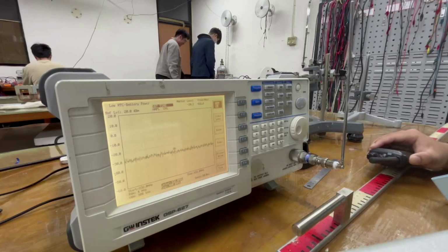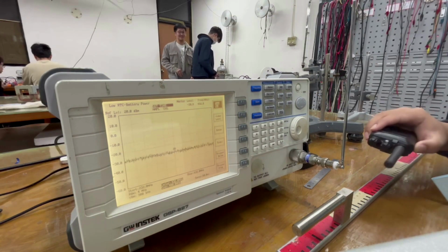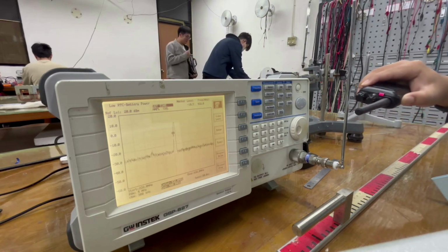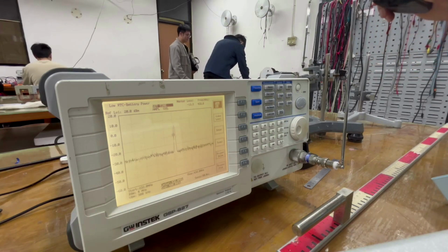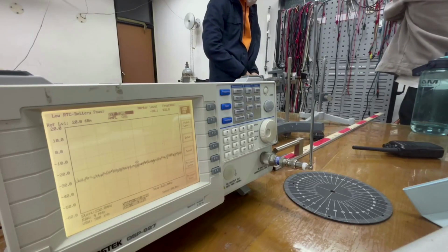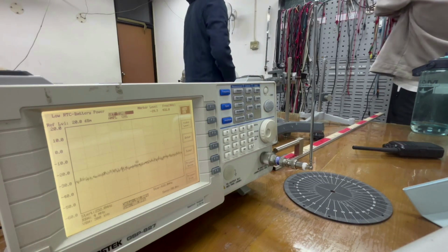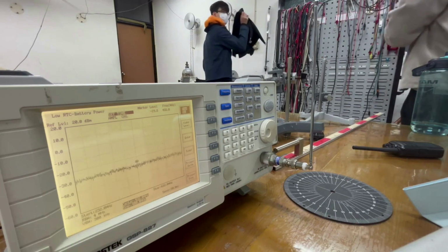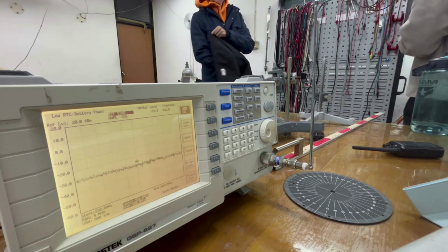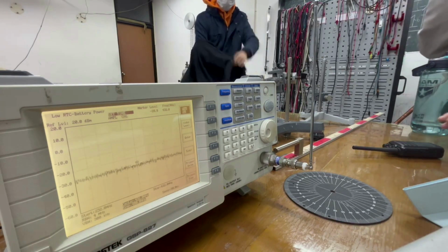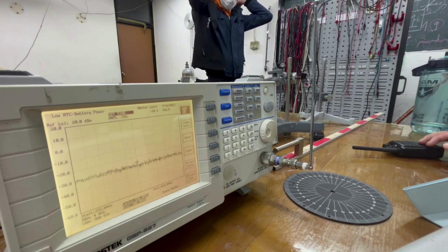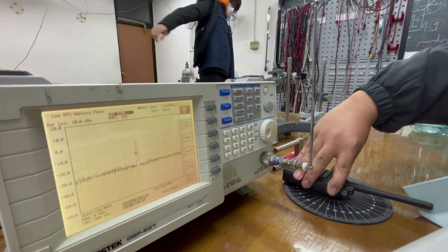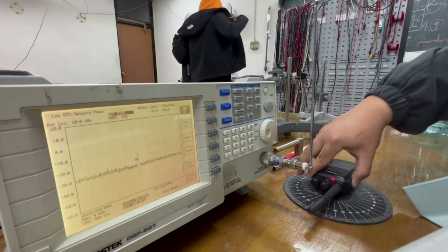Then, we put the walkie-talkie underneath the antenna. By gradually increasing the height of the walkie-talkie, we can plot the intensity versus the antenna length graph. For a dipole antenna, when it is placed parallel to the receiving antenna, the signal strength should be the least compared to a 90-degree angle. So for the last part of the experiment, we rotate the walkie-talkie and measure the data. We can plot the intensity versus the antenna angle graph.